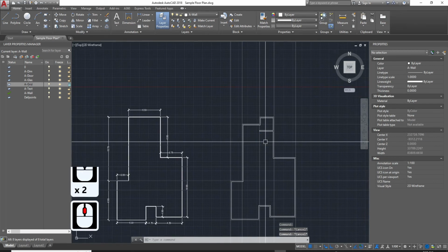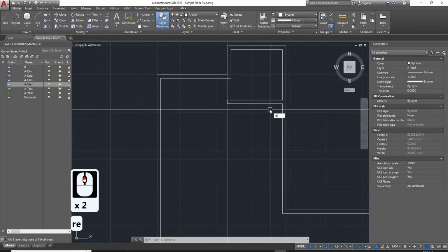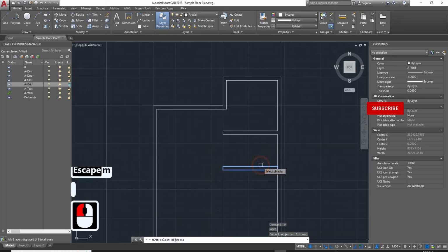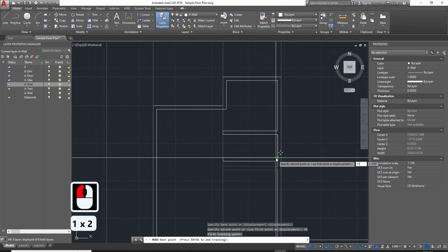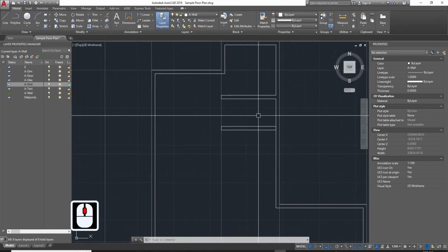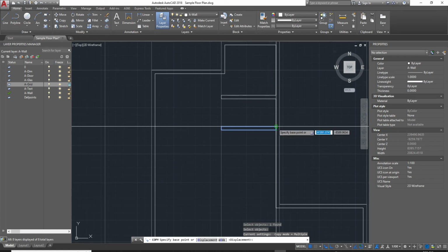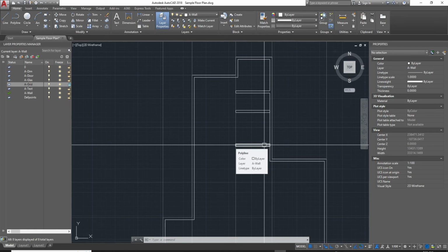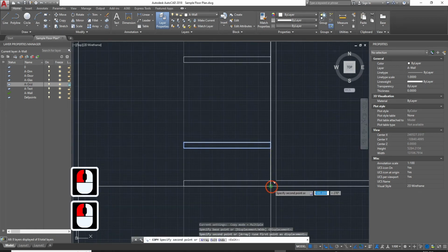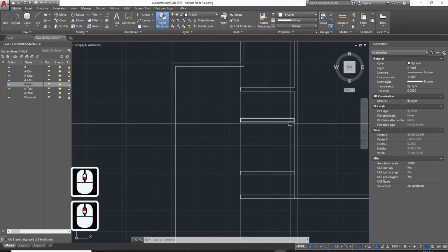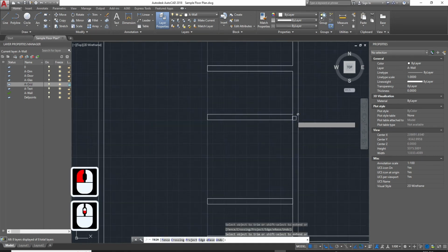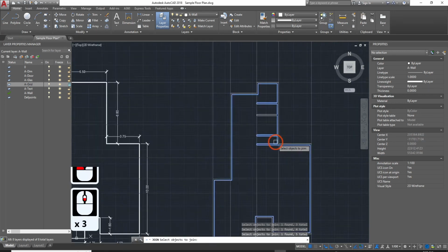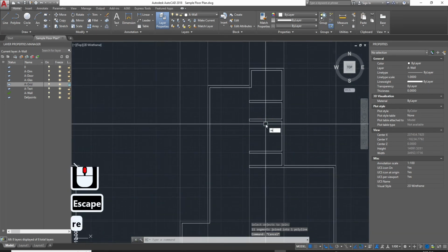This time, I will try to use rectangle command. And copy it to the location I want. And then again of course use trim to delete unwanted lines. Rejoin all the lines, by calling the join command.